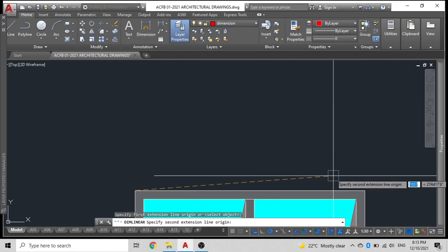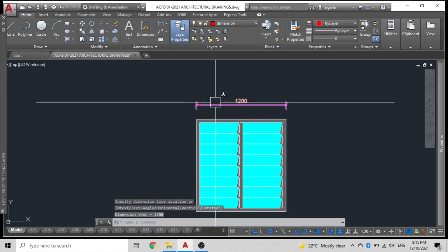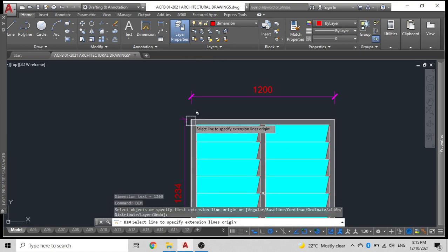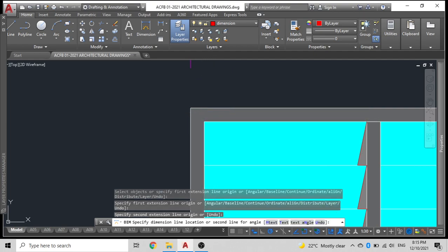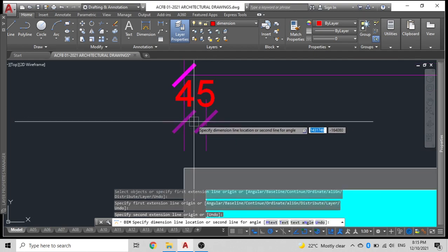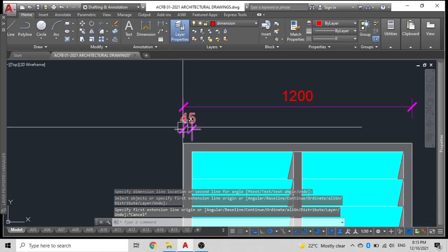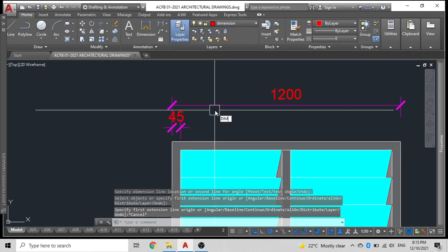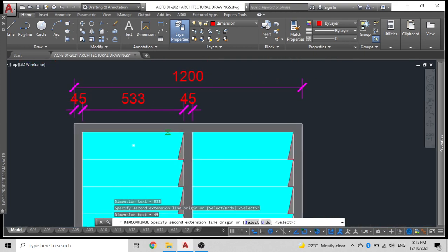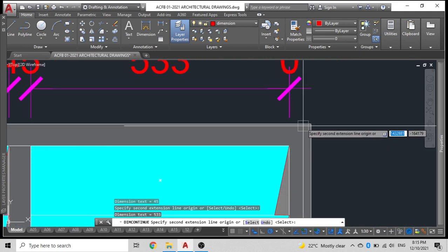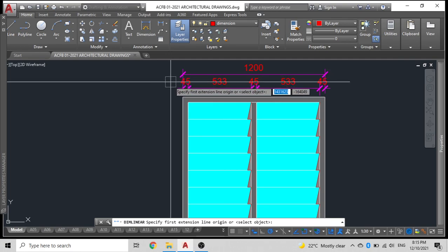Now if you are confident that your work is correct, you can basically put your standard dimension there. And if you feel that it's not correct, you can leave it to the contractor for him to set it up for you, or for him to do the openings for you, because not all dimensions from the drawings can be equal on site. There will be a bit of variance. In my case, since I am sure that I have done the division the right way, I'll basically give the contractor a reference dimension like so. I'll do the same for this.